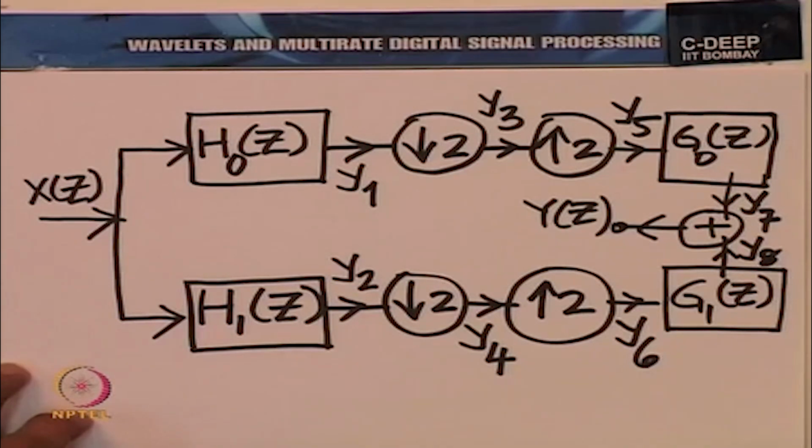So, this is a strategy which we might find useful in some circumstances in analyzing multi-rate systems, particularly when you have a downsampler followed by an upsampler. If you have a downsampler followed by an upsampler of the same factor, it is sometimes easier to go past both of them and then jump back behind the upsampler. We will do exactly that here.